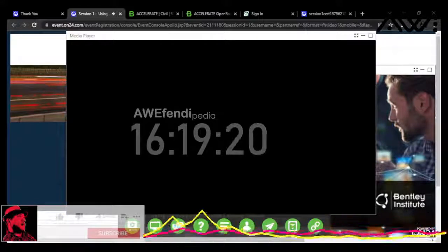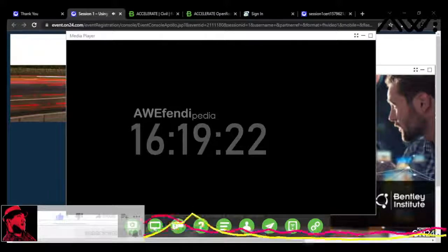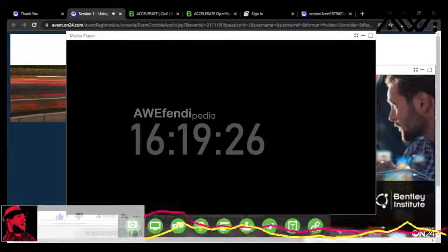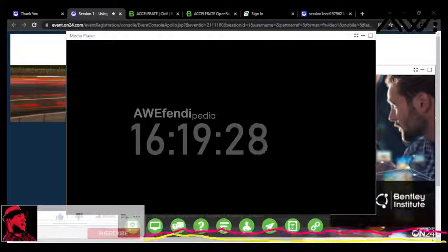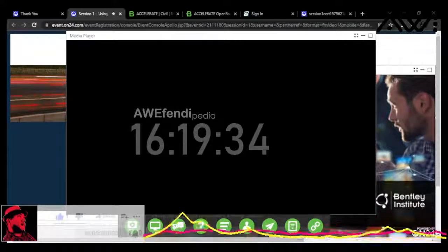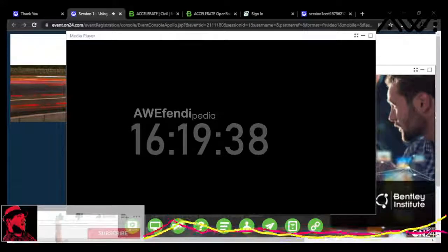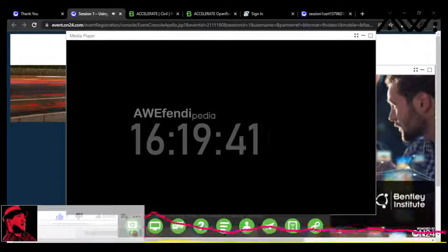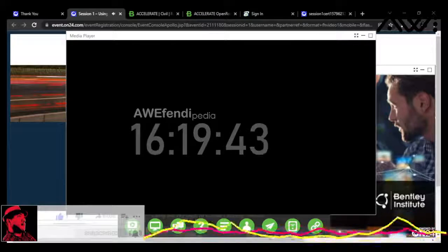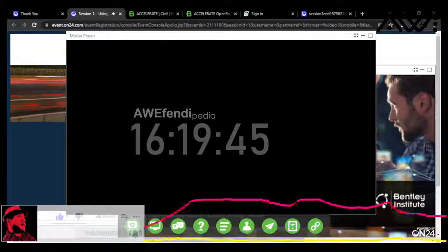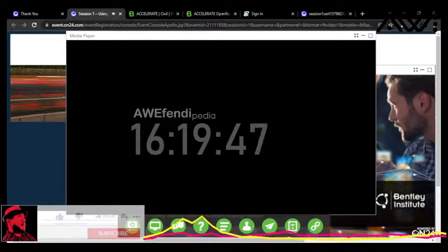And now to clean that up, I want to connect the end of this string to the beginning of our next string. So what I'm going to do is add a control code, a join point code, to this string to connect it up with this string, still using the linking code methodology. I'm just going to write down real quick what number I want to connect it to, 5137. And I'm going to go and edit my point up here. And that shows the string there. The point is selected, and I'm going to choose properties on that.